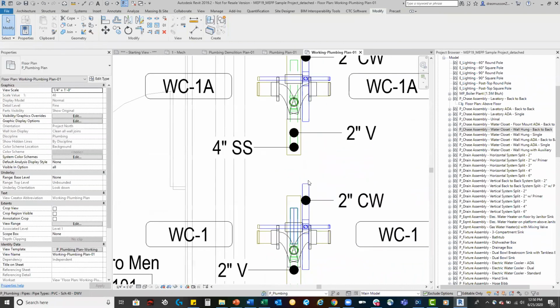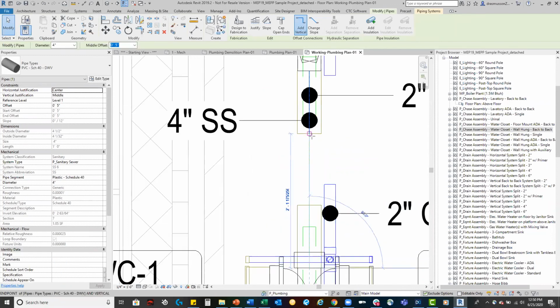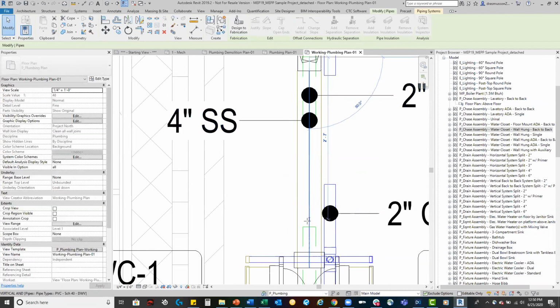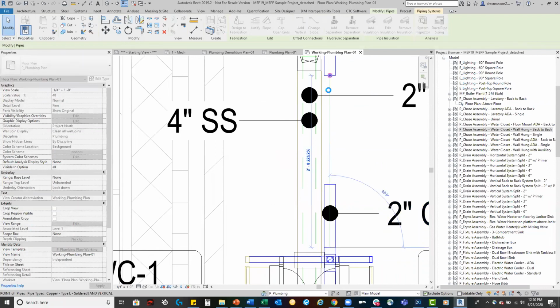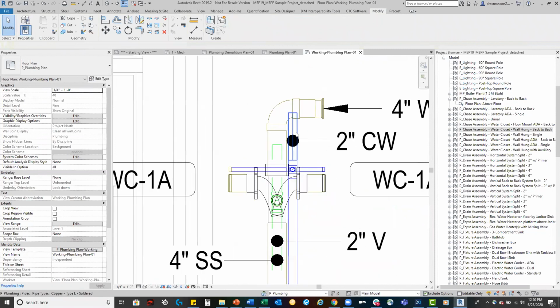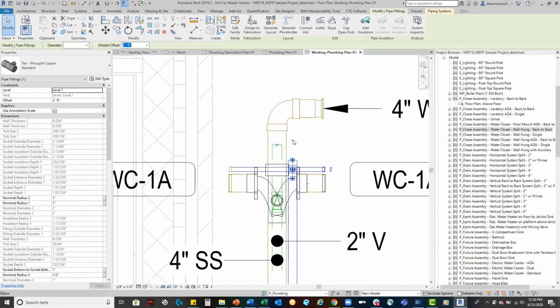Now that they're ungrouped, guys, they're native Revit elements. So I simply drag sanitary to sanitary, vent to vent, domestic. If I'm a good modeler and I'm paying attention, I'm going to delete this pipe and close the domestic system.